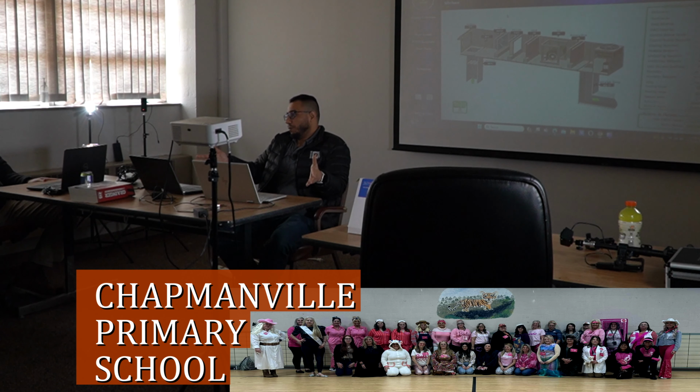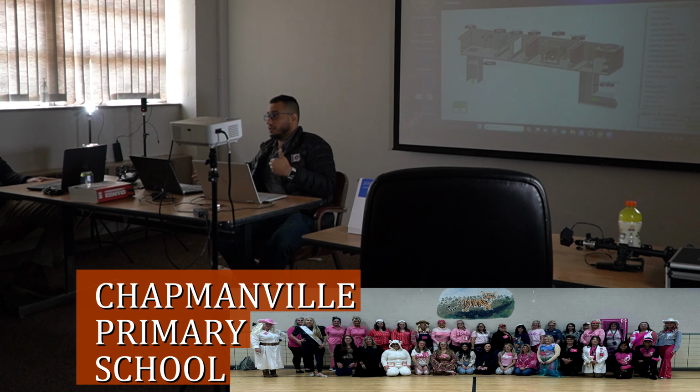But sometimes on the CO2 control, you might have a sub-zero condition, like a very cold day, and the minimum position that you're setting for your equipment is not enough to keep up with the CO2 level in the zone. Even if it's been calculated and balanced, maybe the zone itself is overpopulated. Like you have a room that requires 10 people, and there are now 30, like 40. The equipment does not know whether those people are there or not. It just looks at that CO2 and reacts to that, right?